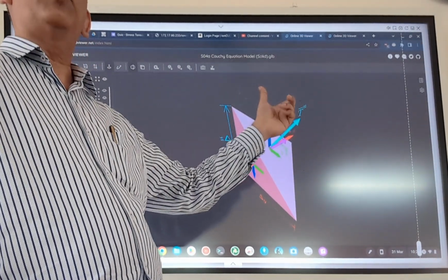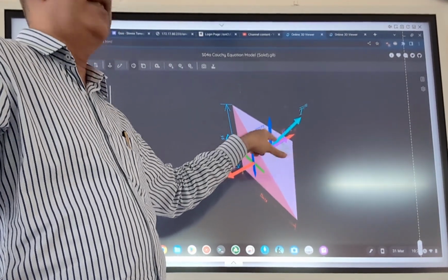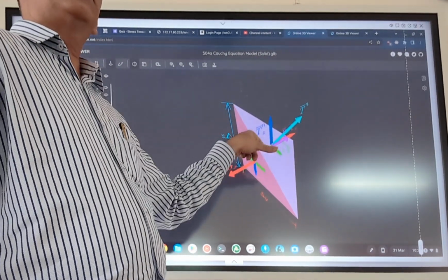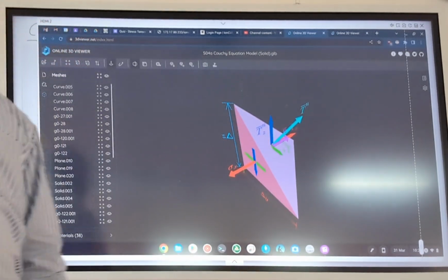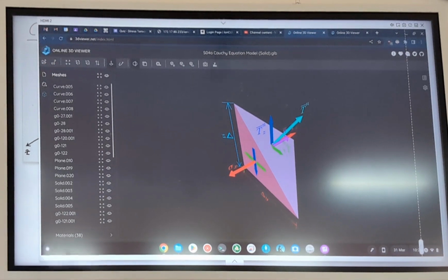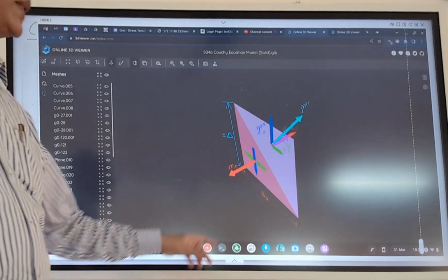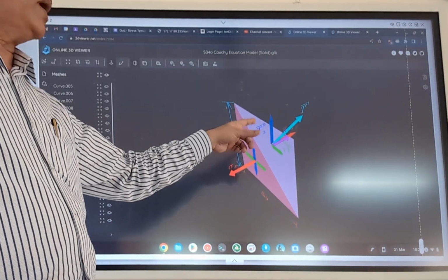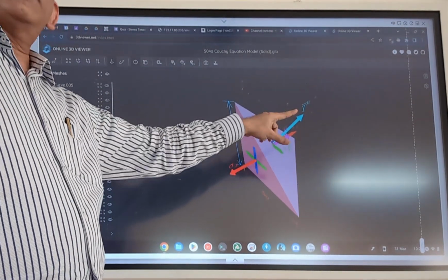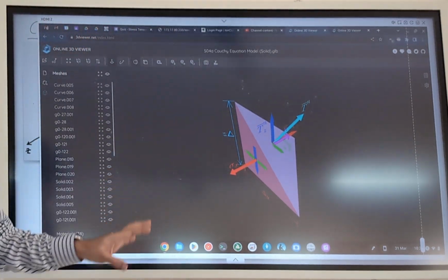So if you can prove that using these three numbers you can get Tn bar, and since this n bar can be any vector, it proves that using these three numbers you can calculate the stress state on any arbitrary plane that is oriented in space. And that is what Cauchy's equation or Cauchy's theorem states. So we'll derive the equations of how you obtain the components of this Tn bar in the x direction, y direction and z direction. So is it clear what we are doing here?